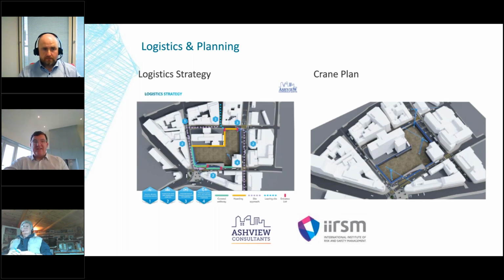And as you said, the mats themselves and the piling mats, or the crane mats that have to go down, who's coordinating all that, so you don't arrive to a crane collapse, God forbid? That's getting temporary works designers in early stages of projects, where the rest of the design might not be completed yet, but there's an advanced work contract which needs to be managed in an appropriate way, and that is not managed well in our industry at the moment, I would suggest.